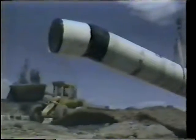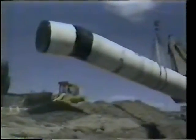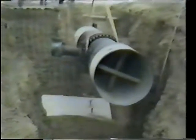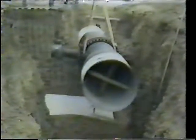Unbalanced thrust can occur, particularly in pressure lines, where there are changes of alignment or cross-section at dead ends, connections, and valves. Preventing movement is done by installing thrust blocks of concrete behind and around the pipe. Restrained joints of sufficient length at these locations can help resist this movement. Steel coupling bands made for corrugated steel pipe can be corrugated and bolted around the two pipe ends to give an integral structure.